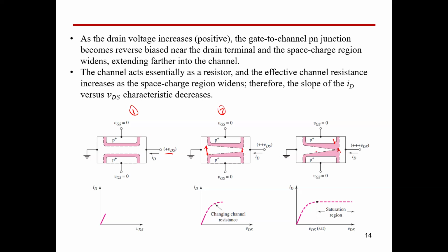And here, with more voltage, the channel width has decreased a lot, and here the channel width is still high. So this means now, guys, we have a nonlinear resistance. The resistance will have a curve like that, and then it will saturate. If you have a very wide depletion region here, it will be saturated.